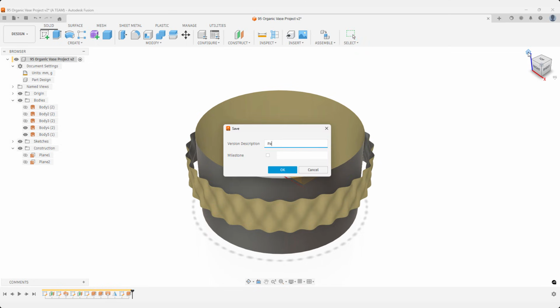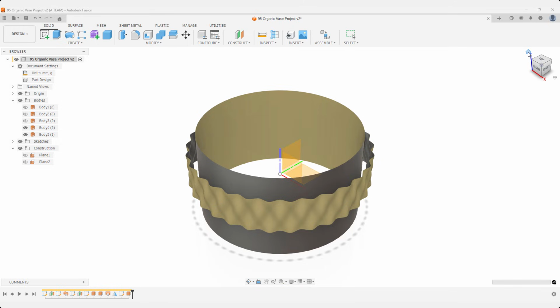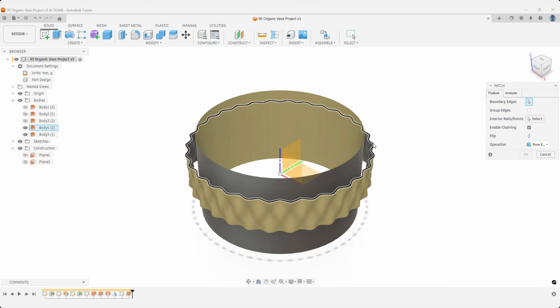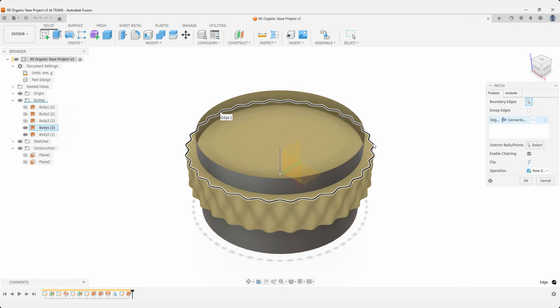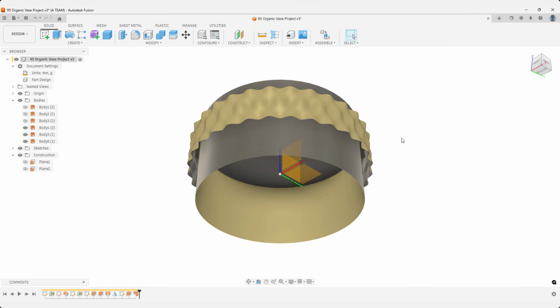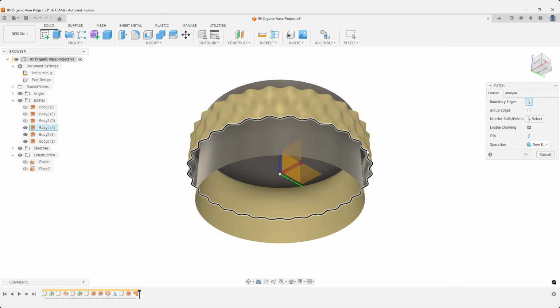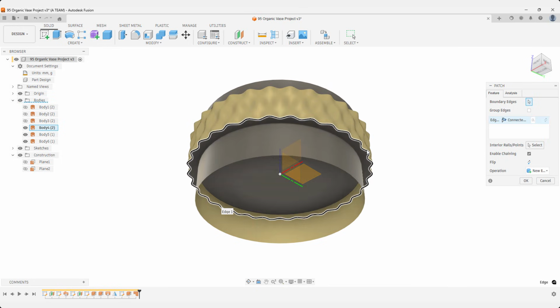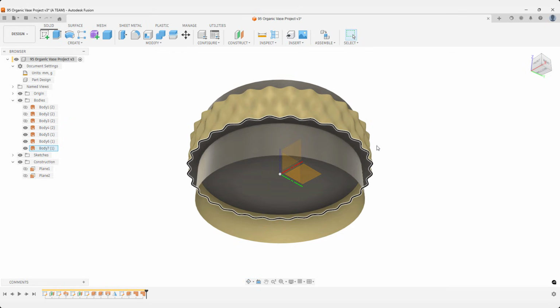I'll save the project again here since the next operations involve complex geometry. Next, patch the top and bottom of the patterned surface model. This closes the surface, which gives us more flexibility to develop the interior geometry. Because we're only working with a fraction of the final model, the computations stay much lighter than if we were operating on the full height, which would significantly increase geometric complexity.